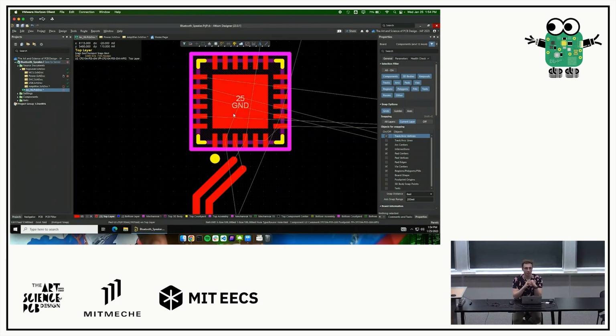So I know someone asked where you shouldn't put a via. Usually in cases like this, USB or on the audio side, when you route a via and you have your trace going to a via, that via is going to have a different impedance compared to the trace that you have. So as the signal goes to that via, it's going to cause weird reflections and all that. So for the most part, you want to avoid it as much as possible.